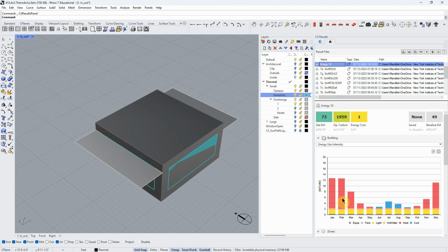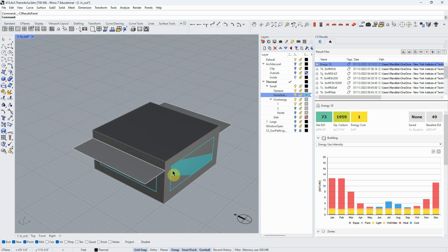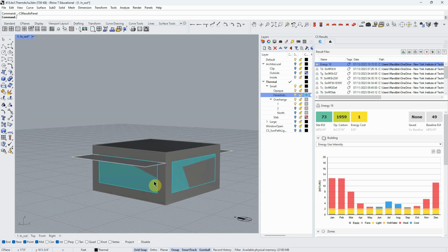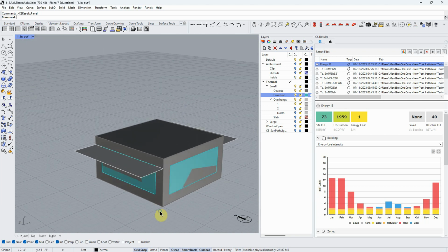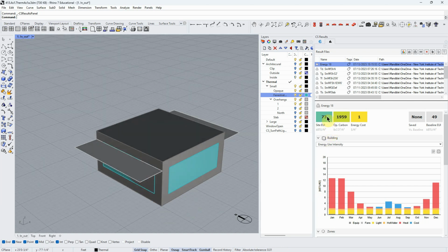However, if you watch the heating load, we have a lower heating load in our previous model. So by shading these windows in the summer, we're also shading them somewhat in times that we were gaining heat during the winter, and so we don't get as much of a benefit as we do get a reduction in cooling load.